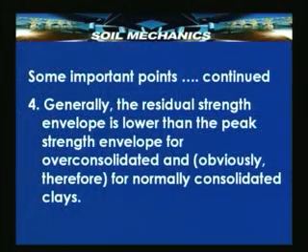The residual strength incidentally is independent of the stress history. It is only proportional to the effective stress that is applied, and you can see that in fact the residual strength remains almost practically constant with displacement, and irrespective of what stress history the soil has experienced, it will eventually have a certain residual strength beyond a certain level of displacement. Generally, the residual strength envelope is lower than the peak strength envelope for over consolidated, and therefore also the normally consolidated clays.